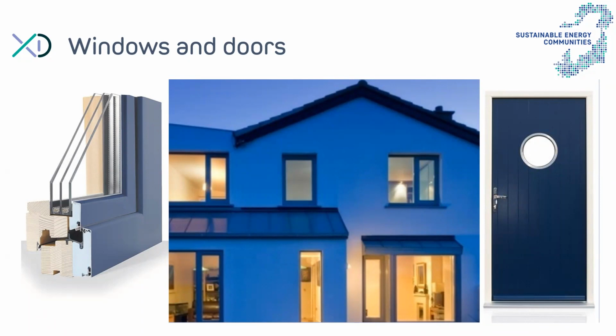But in some cases, you could consider upgrading your existing windows if they're in good condition, and if they're of a reasonable quality and insulation value. Well, then simply refitting them, so making sure that they close properly, that the seals and the gaskets are all in good condition, or maybe repaired in some cases. That's a low cost measure, but that can really improve the performance of the windows and the doors without any major investment involved.